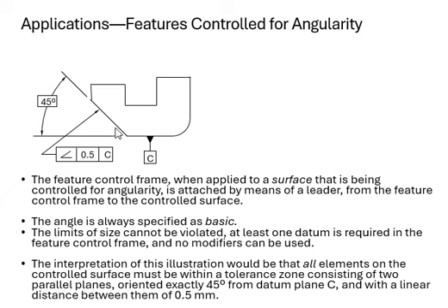We want to know the angle of that surface measuring from this reference plane, which is the extension of that surface right there. So we're going to put datum C, the controlling datum reference, in a primary datum box right there, because only a single datum is going to control, meaning we're going to measure from here to there.